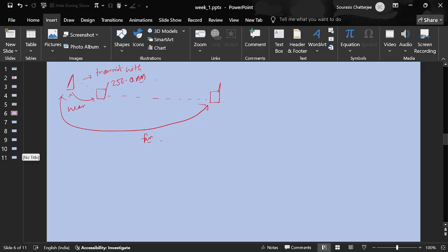So as you correctly pointed out, the channel changes, your SNR drops. Now the MCS index should be much lower, maybe QPSK or even BPSK, with which you can decode the message with arbitrarily low probability of error. But the base station doesn't have this information yet.